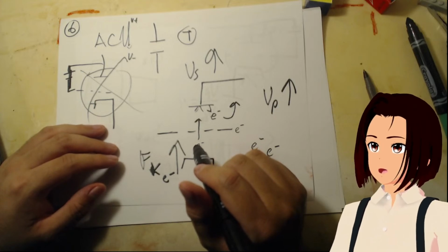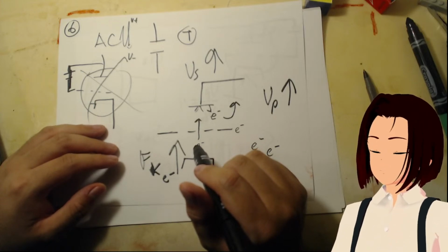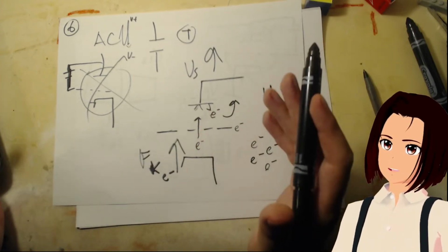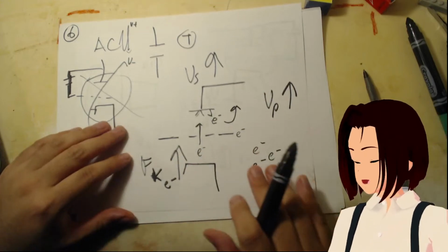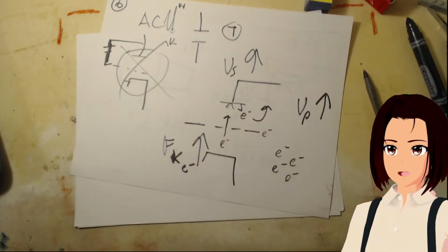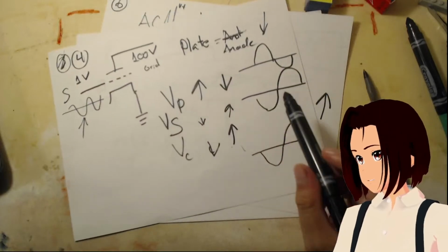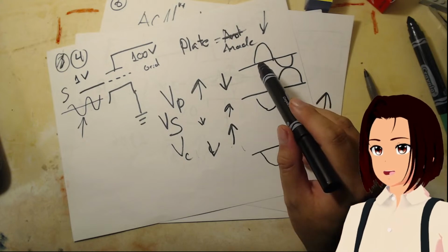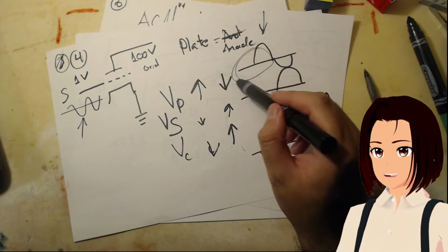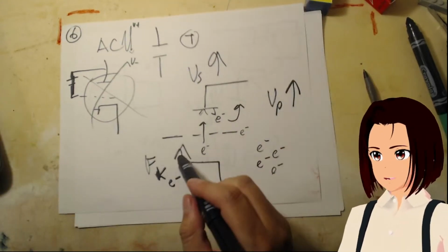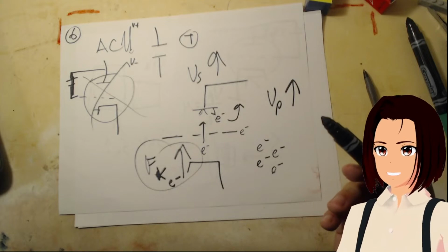But they're pretty good for phase inverters. Triodes are fine for phase inverters because you're not really amplifying a lot. You're just flipping it, because you saw in this that it inverts the signal, so you can use that in another part of the amplification circuit. So triodes are good for that, but because of the other issues, triodes kind of suck.